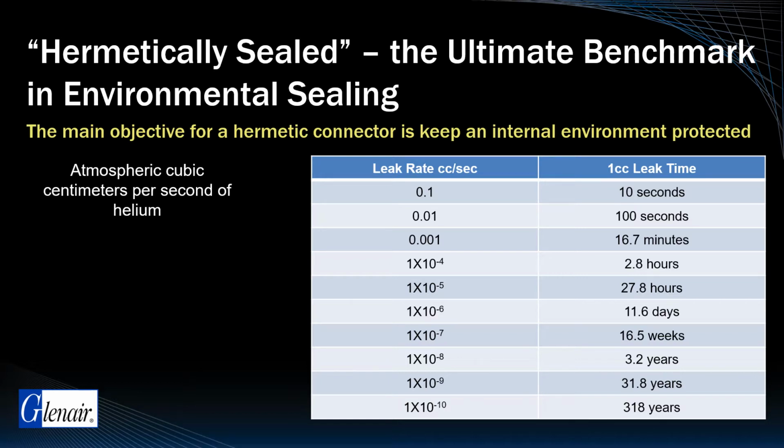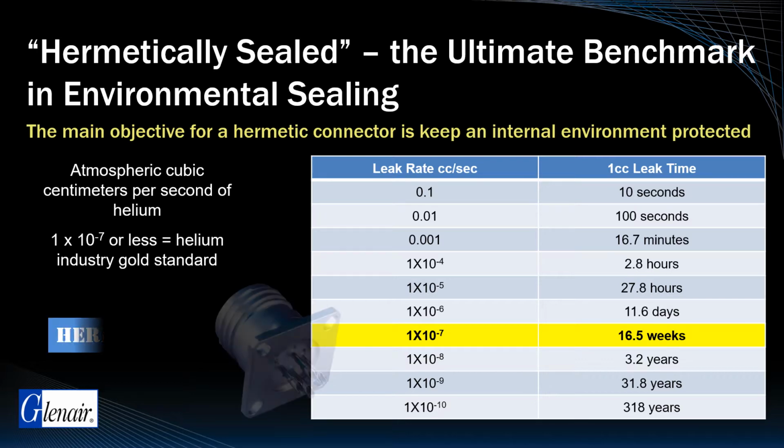DLA mil-specs define a leak rate measurement of 1 times 10⁻⁷ cubic centimeters of helium per second as the standard acceptable leak rate for our industry, and any technology that can maintain that standard over the service life of the connector is considered to have met the hermetic seal standard.